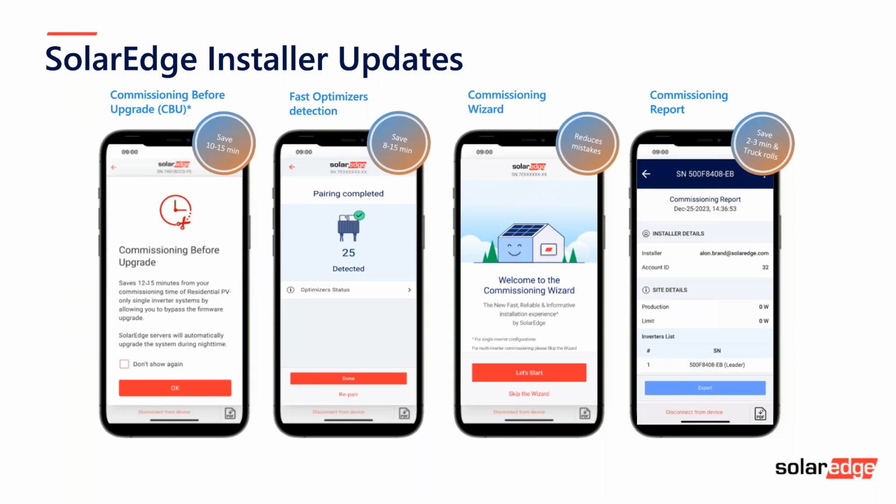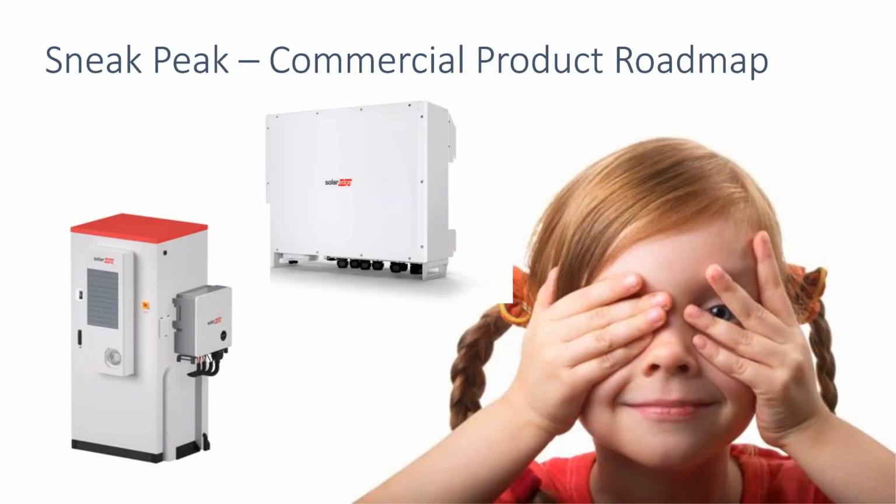And what's also going to be coming through reasonably soon is a new way in which you can commission a system. You don't have to wait for everything to complete before you go to the next step. You don't have to wait for the optimizers to complete pairing before you go to the next step. You can do everything all at the same time. So you can set off the optimizer pairing and then go to setting up your grid codes or whatever. So again, it's really trying to help speed up the process for installers.